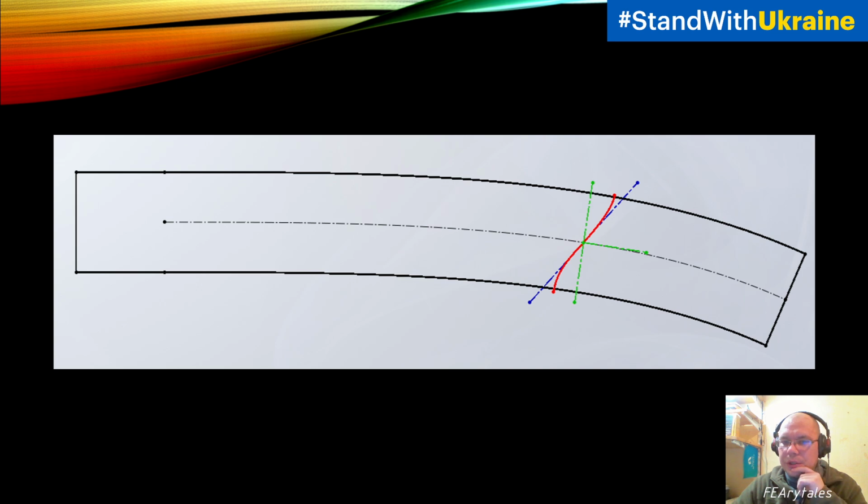we need to use the Timoshenko theory, which says that we need to use an additional derivative for obtaining this angle, which is shown as the blue line. It means that our section is not normal, but has an additional angle. In real life, when we talk about real geometry, we need to understand that it will look not like the blue one, but like the red one. It has a very strange deformed shape, and even this shape will not be symmetrical here and here.